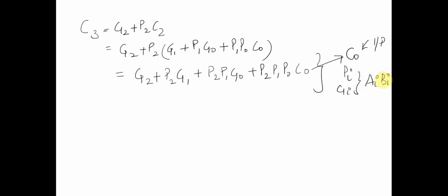So basically we can calculate my final sums and intermediate sums in one go. And these expressions are all sums of products, so we can use them to make a circuit with only two levels of delay. This is like one OR gate, which ORs all the terms, and these are AND gates, and all these AND gates form one level of delay.